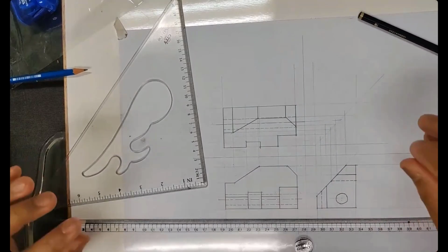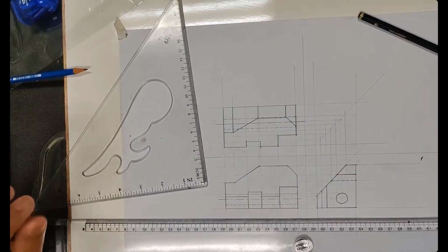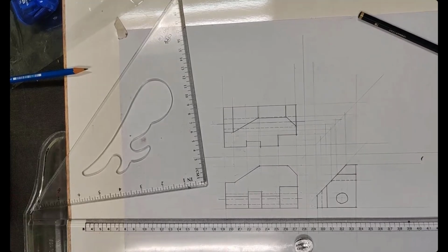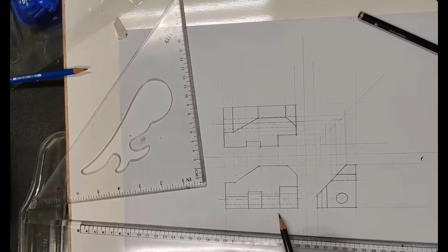Because why? The point of dimension is to facilitate the reader, the fabricator, the manufacturer. Because when they want to fabricate these jigs and fixtures, this is a block. The manufacturer, the machinist down there, you have to make it easy for them to read your drawing. Then only they can do the machining. Now the top view clearly shows the dimension of the cutout. Do not combine the 20 and 10 with front view and side view. That is a totally bad mistake. You are not facilitating the reader to read your drawing.